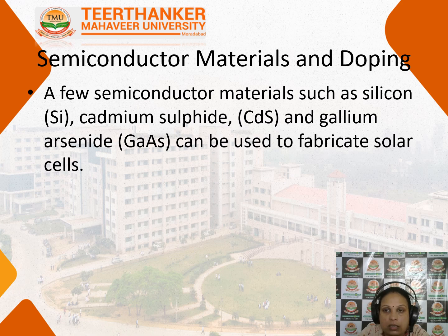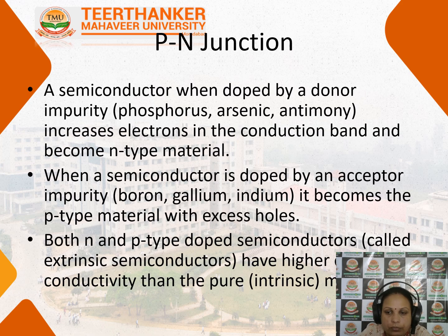So silicon is actually a semiconductor, that is, a half conductor. It needs to be doped, meaning doping is done. Silicon is added with some doping material. Now in the solar cells, the PN junction is created. A semiconducting material, when it is doped with donor impurities, the doping materials being phosphorus, arsenic and antimony, is used for doping the semiconducting material, that is silicon.